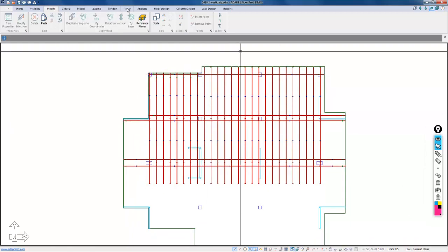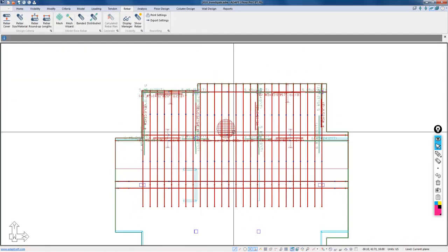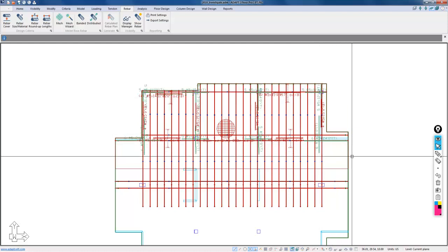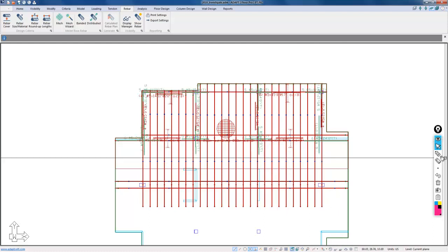And we have our rebar. If I go back to rebar, show reinforcement, we have our rebar in that end span. So now we want to evaluate the slab. To evaluate the slab for stress and for capacity, we have to generate design strips. So we're going to create what's called a support line in the X direction along this path, along this frame line, and along this frame line. And by doing that, the program will be able to break this up into a tributary.